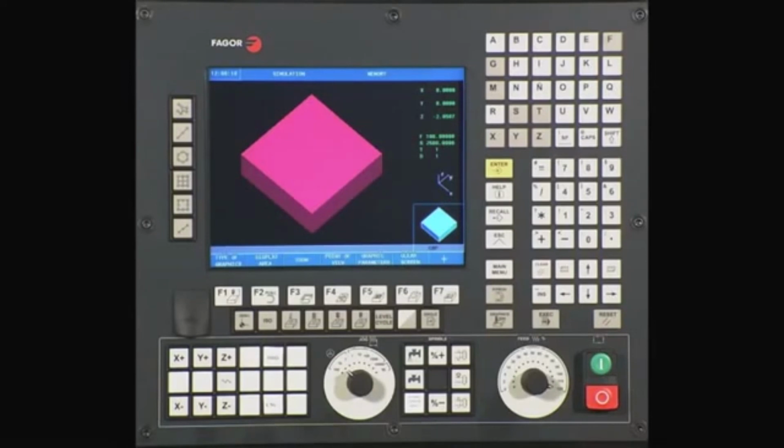You will now see solid graphics on your screen that represent your workpiece. For safety reasons, turn down the feed rate to 0. Press cycle start and now turn up the feed rate to 10%. The CNC is now simulating the part being executed. If there are any errors in our operation, they will appear here. To speed up the graphic simulation, turn up the feed rate override. The operation is complete with no errors.